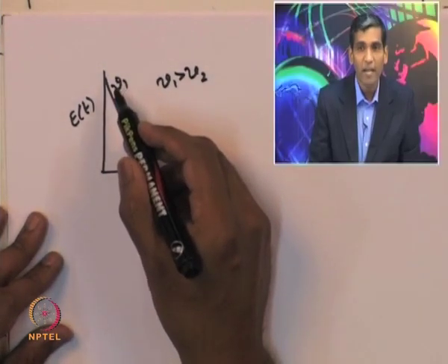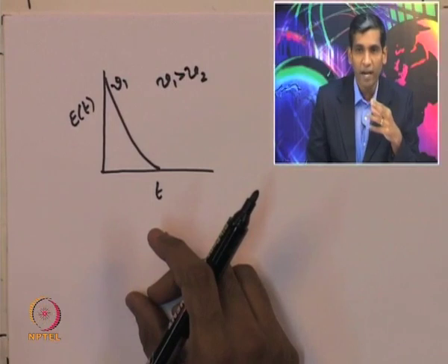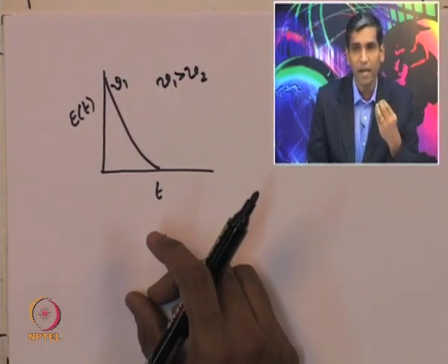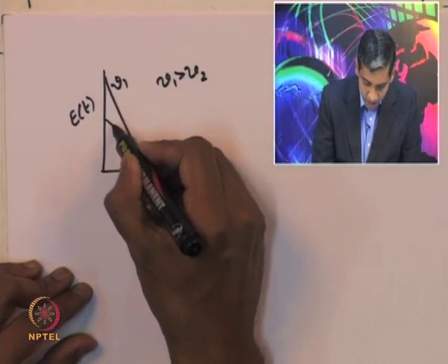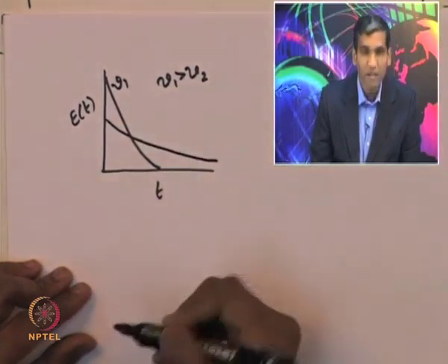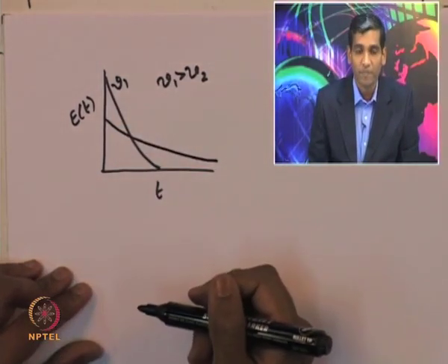Okay. Then the amount of time that the fluid stream spends inside the reactor is going to be larger, because the volumetric flow rate is lesser than V 1, and as a result the E curve would look like this. The slope of the E curve will correspondingly change.